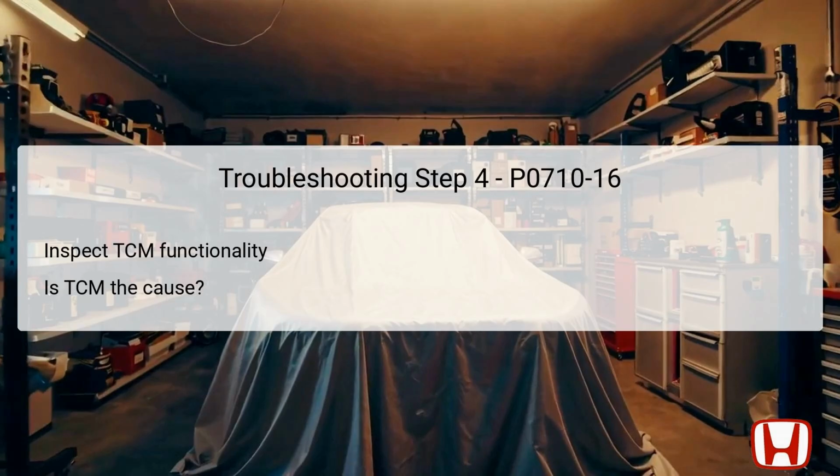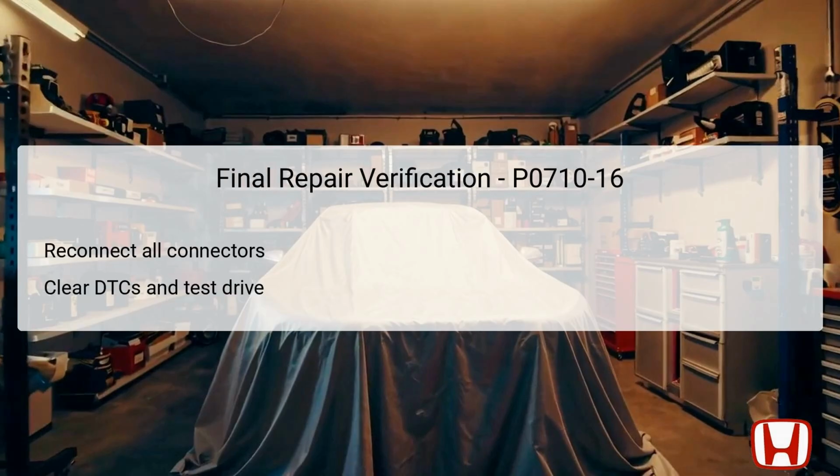Technicians may need to utilize advanced diagnostic tools to confirm the TCM's functionality further. If found faulty, replacement or reprogramming may resolve the issues, ensuring that the transmission system operates effectively. After completing the necessary repairs or component replacements, technicians must perform final repair verification to ensure that all work was successful. This involves reconnecting all previously disconnected connectors, ensuring proper seating and secure fit to prevent future issues.